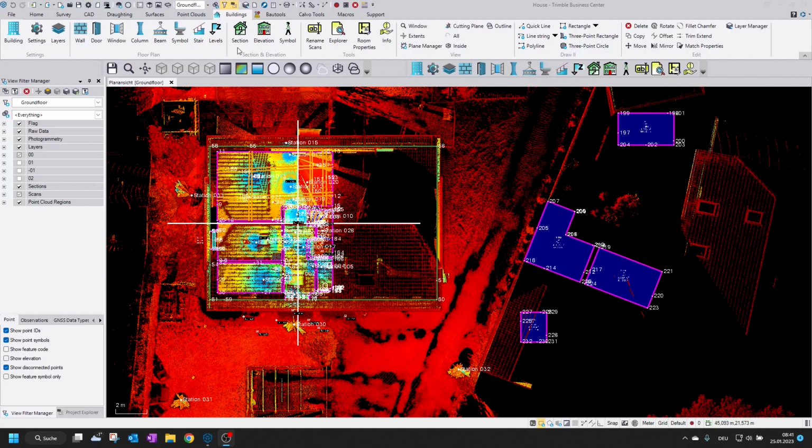Okay, then let's see now this section and elevation. So both are similar, so we will create a section or an elevation by picking 2 points, left and right, and then the software will create a vertical section cut or cutting plane, and we will pick on this vertical cutting plane the points that we need, and the results will be created on the 2D view. So we are much more flexible to create the additional elements or to edit them, on extend, trim, or whatever we need.